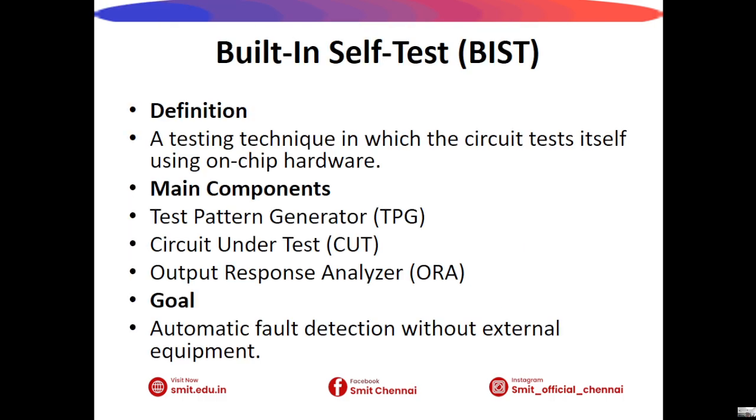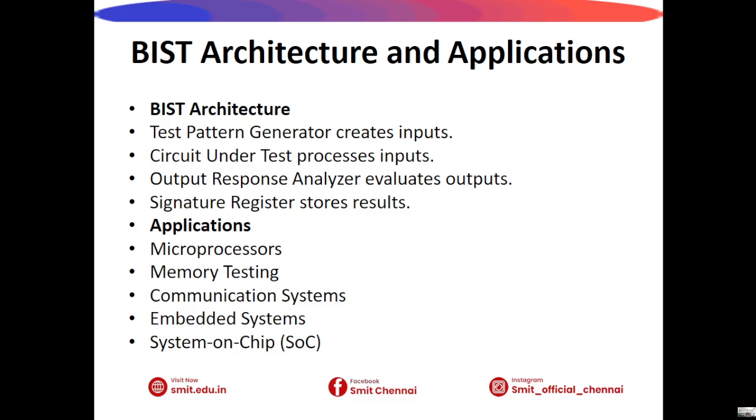Next we see about the built-in self-test. Built-in self-test is a technique where the circuit contains its own testing hardware. Instead of relying entirely on external testing equipment, the chip generates test patterns and analyzes responses internally. This approach is particularly useful for large and complex integrated circuits where external testing can be expensive and time consuming.